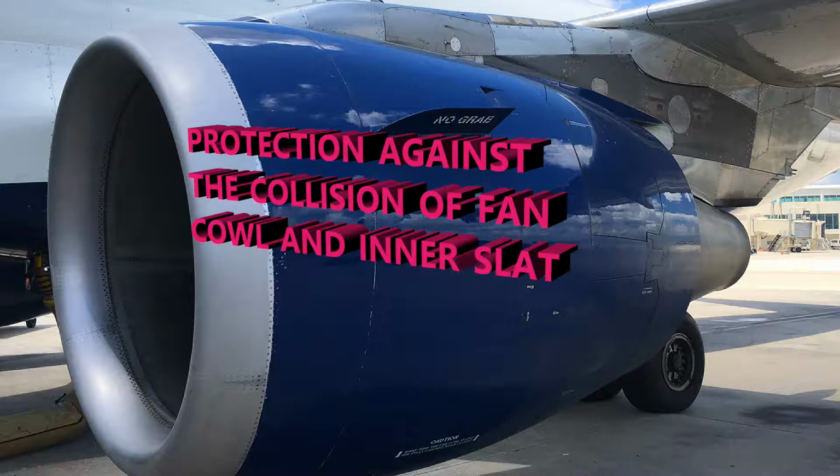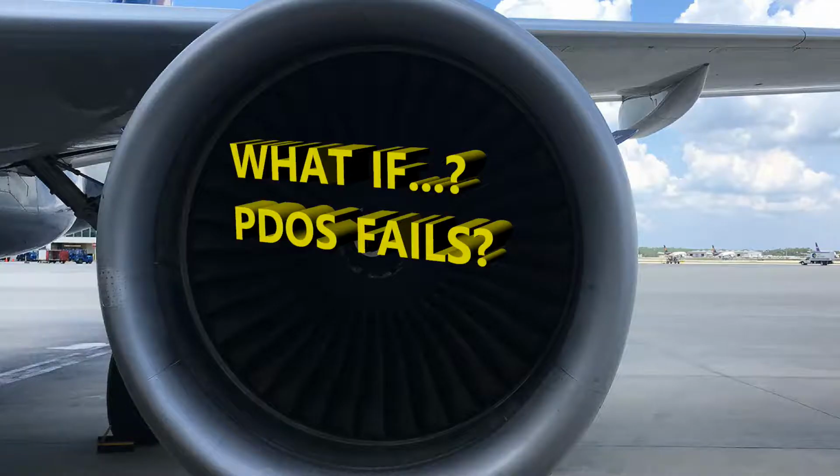All right. Now let's just say that for some reason you have a failure of the power door opening system, then you could actually manually push the fan cowls to an open position. That is possible, just so you know, in case you didn't know that. But that's your last resort. There's a quick disconnect that's fitted to each of the opening actuators. It lets connection of an external pump be available there, okay, to help out.